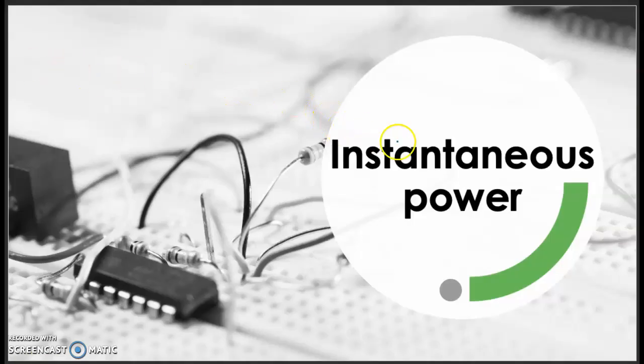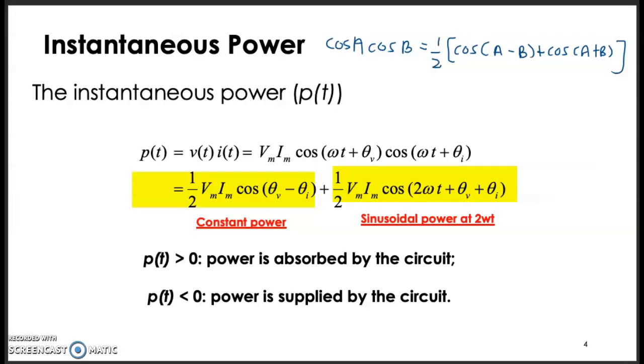Okay, for the first one, we call instantaneous power. In your previous chapter on DC analysis, how you calculate the power is P equal IV, or P equal V squared over R, or I squared R. This formula applies for DC analysis. Now, how about AC analysis?